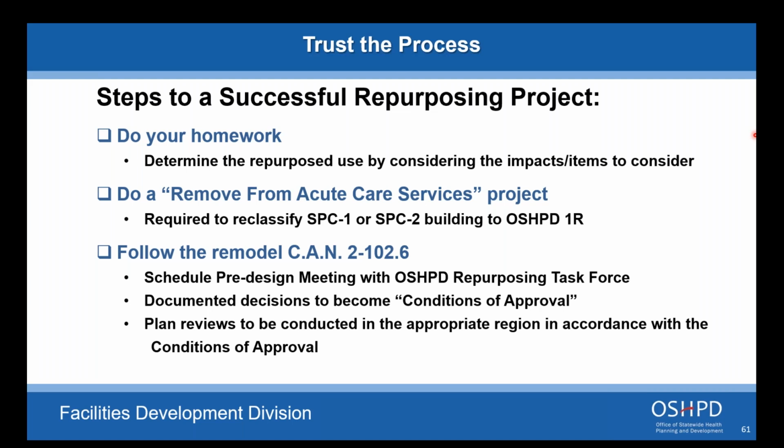Once that work is done, what we typically would see is, again, either a project or several projects to start rerouting or making safe the utilities that are spanning from one building to another, putting in expansion joints or flex joints or automatic shutoffs or quick shutoffs on there.